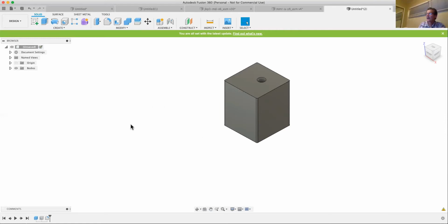Again here, maybe I want to groove down this thing. I'll still create this thing first. I'll come along and go, okay, I want to groove. I'll do a whole bunch of features in this that could all be in one sketch and one extrude. But my design intent is that those all have specific functional reasons for existing. So the overall body, I'm designing it to fit into something. Then there's a groove or a slot. Hey, it's to go do something else.